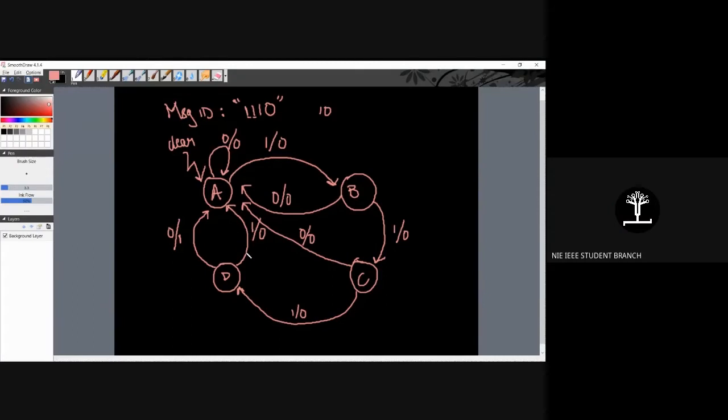Yeah, I get your question. There are two things called overlapping and non-overlapping. If it is overlapping, I would probably stay in the same state and wait for a zero. But we are doing a non-overlapping sequence here. I forgot to say that in between. You can do that also. There are absolutely no restrictions.